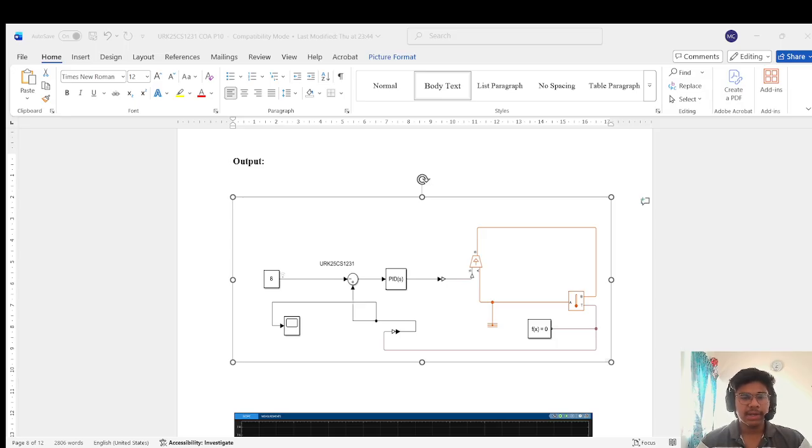Next is the signal conversion, from Simulink to the physical part. The small arrow-like block after the PID is the Simulink-PS converter, which converts the mathematical signal to the physical signal, which means the logical signal to the physical signal. Next is the physical system, the orange part of the Simscape, which is the actual plant system being controlled.